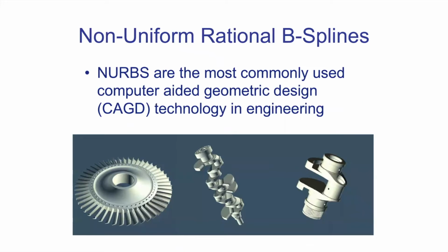Now, the most important tool, I would say, in CAD design, beyond B-splines, are rational B-splines, where you take their ratios. And the good thing about rational B-splines is you can make use of certain facts about conics and B-splines in higher dimensional spaces and projective transformations. And with them, you can get explicit formulas that represent all conic sections, circles, ellipses. These are NURBS objects right here. And that precision, of course, is essential for engineering.